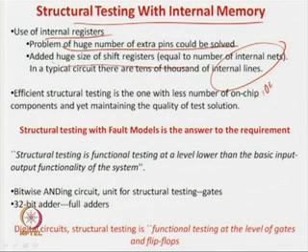If there are, say, 10,000 internal lines, then you may require on the order of 10,000 flip flops in each shift register. That is, for each net you require one element of the shift register. A shift register consists of flip flops, so one flip flop per net to be controlled. That is also very high in number, but still it is less of a problem than the pinouts.